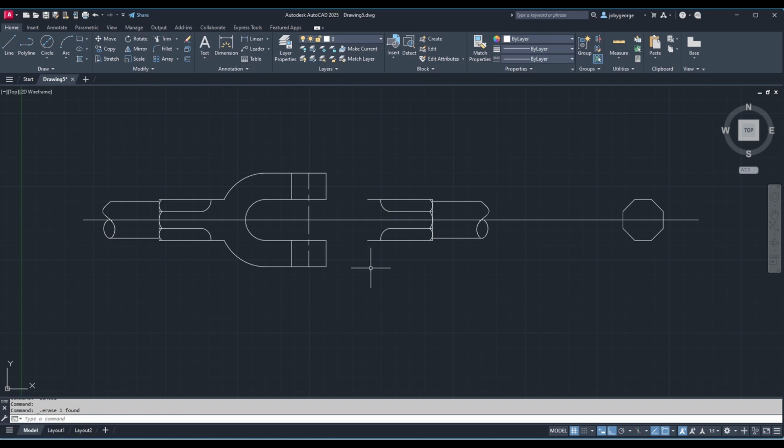Now I will use the distance of 24 from the center, the other point of the end. So you can always draw 24, and I am finishing it here. Now I'm going to extend the remaining lines to the line which I have drawn now. Okay, so this line as well as this line I'm going to extend.